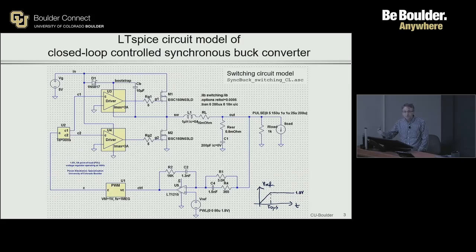What is ultimately the voltage we want the output to be regulated to? 1.8 volts, right? And in the simplest of all cases, you could just give a DC voltage source of 1.8 volts right here, right? That's what you could do. Why are we doing this stuff right here? Why were we ramping this gradually from 0 to that 1.8 volts?